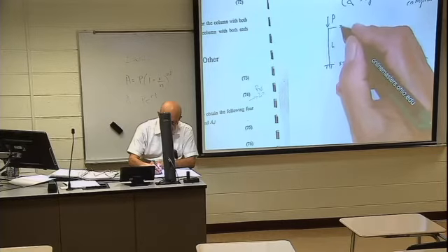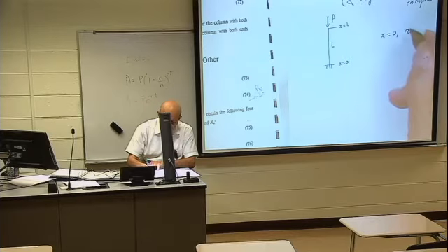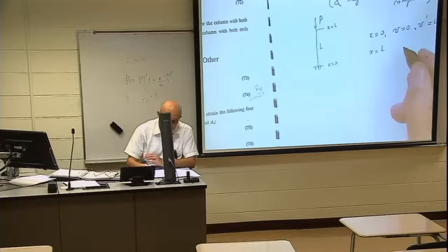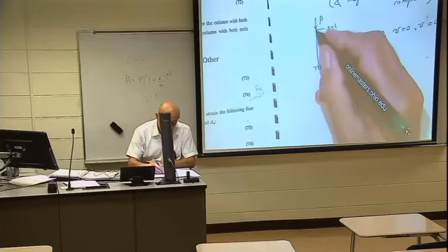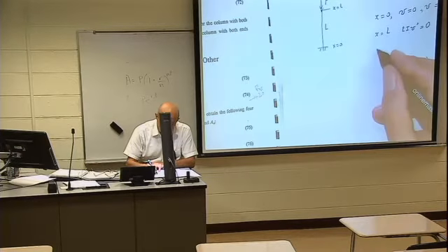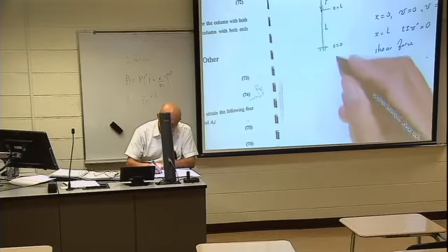Here x equals L. So at x equals 0, we have V equals 0 and V prime equals 0. At x equals L, bending moment, of course, is 0, and that means EI V double prime is 0. And then shear force. We will leave here one space.